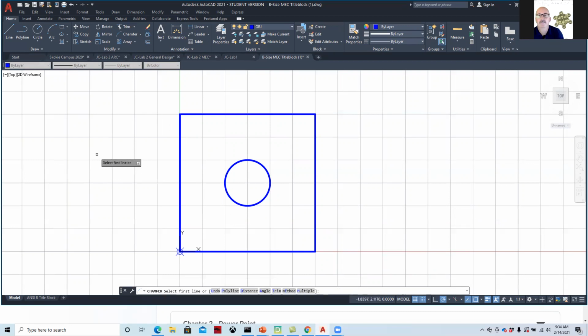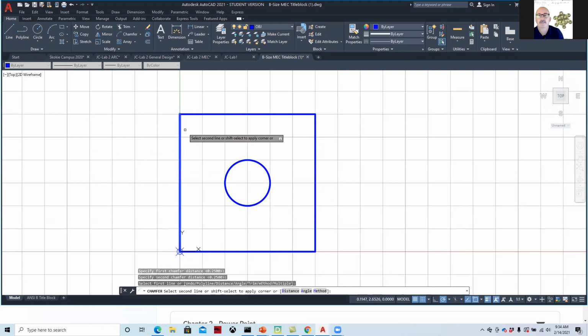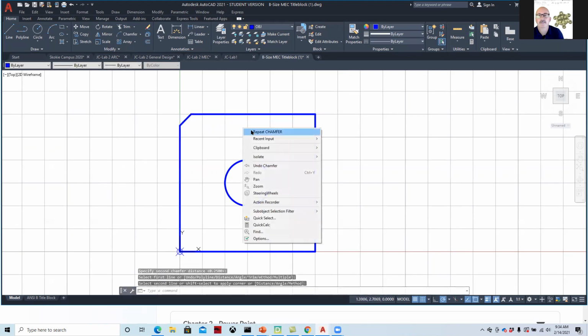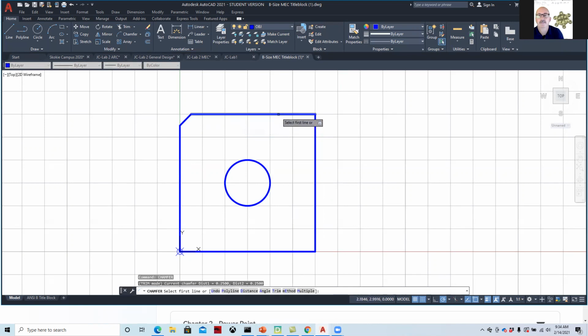And so you can type everything in, or you can use the down arrow if you have to learn to read the interface, and I can then set up that is a 1/4 inch chamfer. And so I'll say distance 0.25. They're already in the defaults for the template I created. And so unless we're changing this to maybe a 1/2 inch or something else, it remembers the last coordinate.